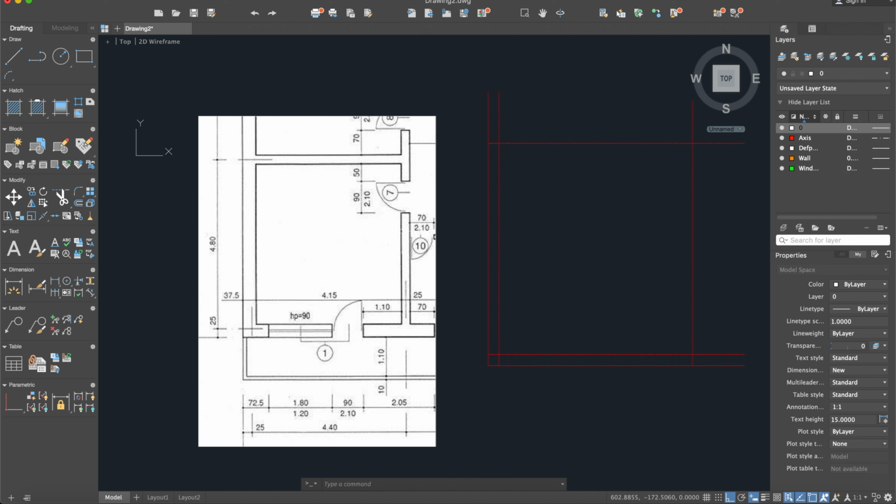And now, because these walls are interior walls, I will use the offset command again, but this time with this difference, 35.5 minus 25. So I will put the offset with 12.5. So offset 12.5. Okay.